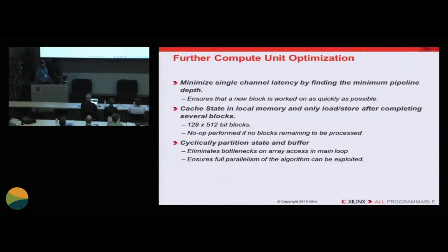So the other issue that we had to look at was trying to minimize overall latency for a given length of a SHA-1 input block. So if you have 8,000 characters coming in that need to be hashed, you actually need to do the first 512-bit block, and then you immediately need to get to the next block, and immediately to the next one, and so on.